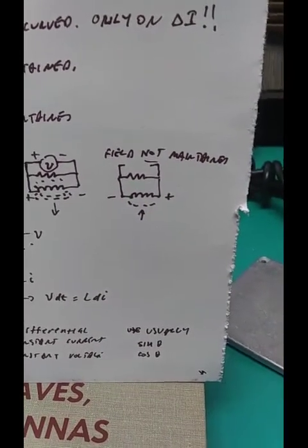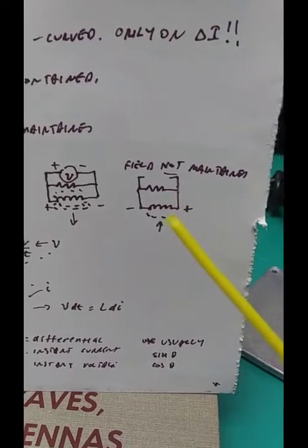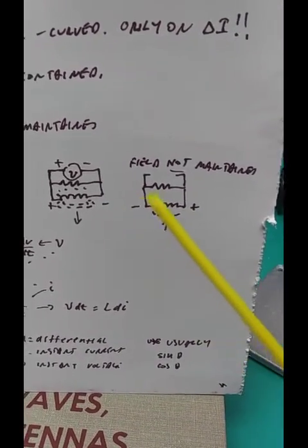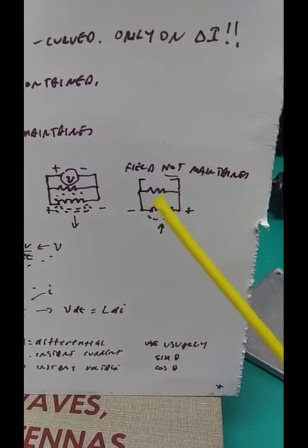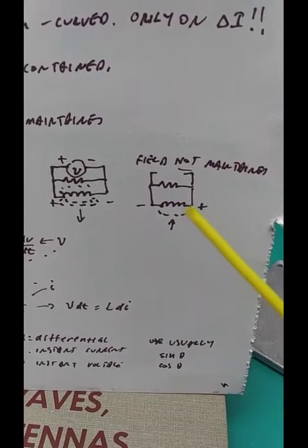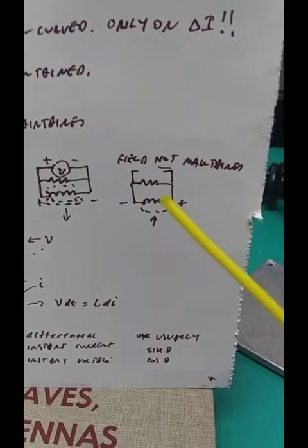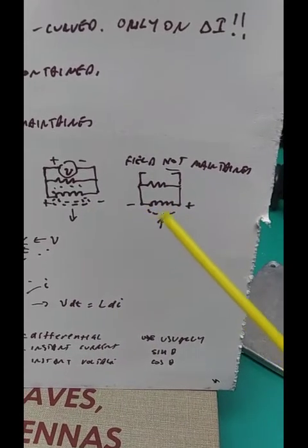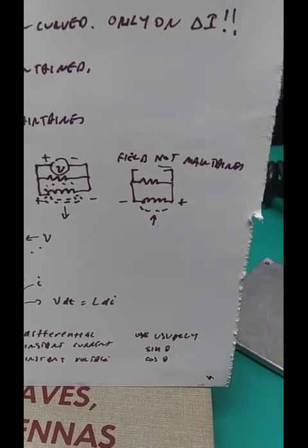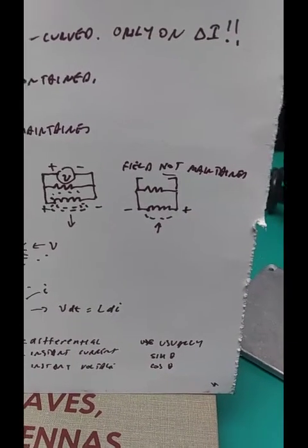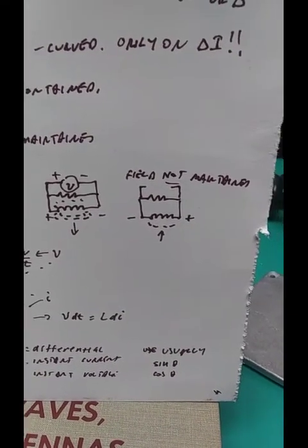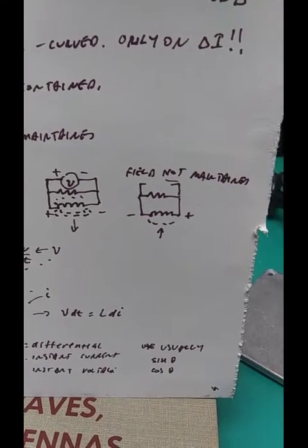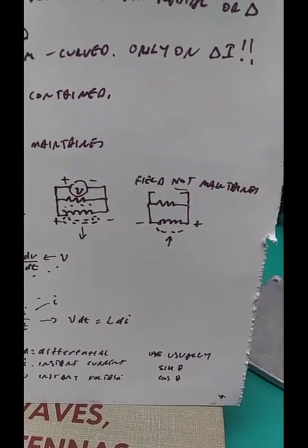Maybe the most elementary form of an antenna is this inductor with a switch. Not a resistor, but a switch, where the switch applies a voltage source, causes a current, the magnetic field charges, and then the switch opens infinitely fast so that no arcing occurs across the switch contacts, and no energy returns to the circuit. Where does the magnetic field go? It doesn't fall on the floor. That's not the dust bunnies we sweep up and throw in a trash can. That energy is emitted off into space. The common term is radiated.